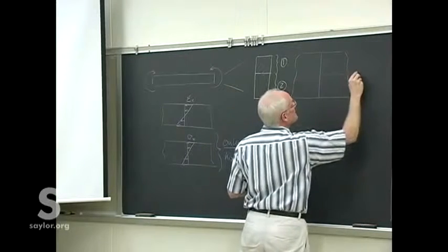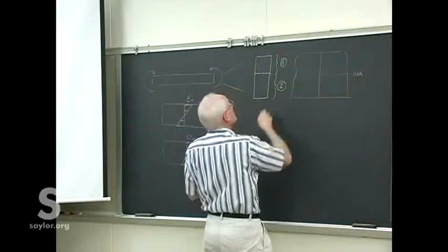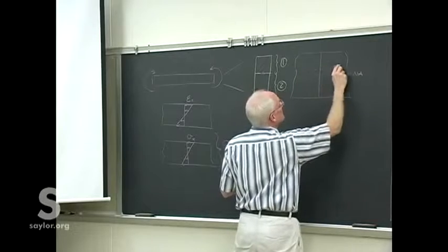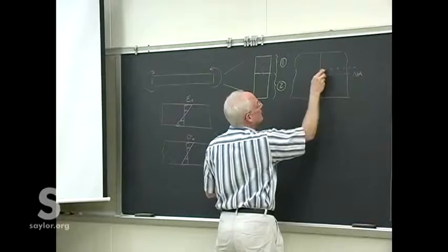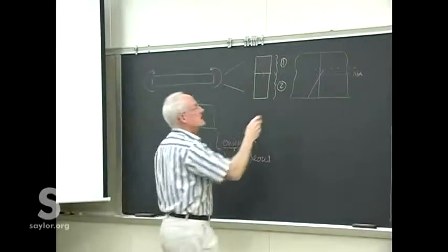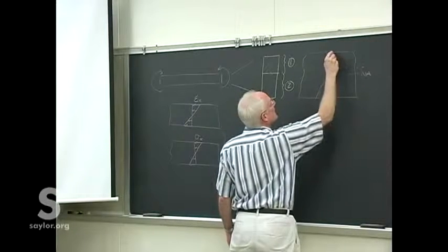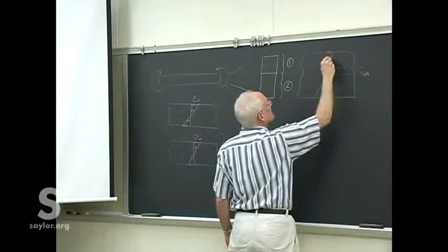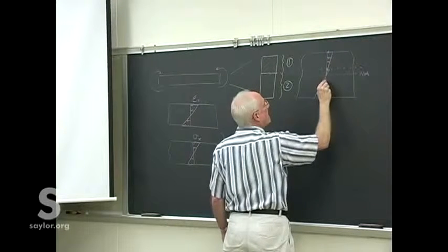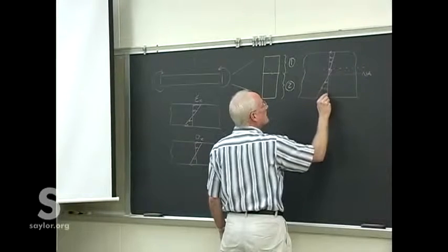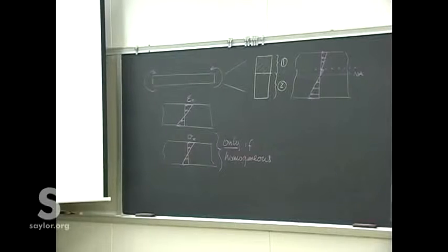Wherever the neutral axis is, we know that it's linear through there. Here's our second material across there. So we know it's linear through there, but now we have a different material that would have some different type of stress and have its own distribution that would look something like that.